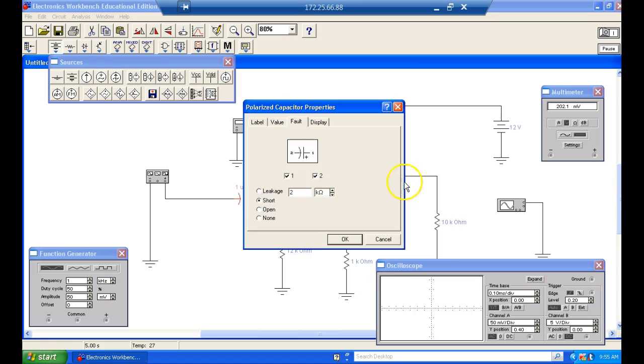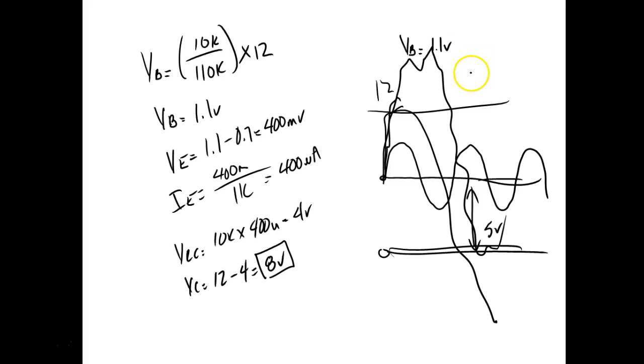So when you measure a capacitor with an ohm meter, what should it measure? Should measure what? Infinite, yeah, unless it's a big capacitor. What happens, a capacitor, it stores DC, right? You understand? So when I charge the capacitor up with my meter, we'll do this. We'll just charge one.